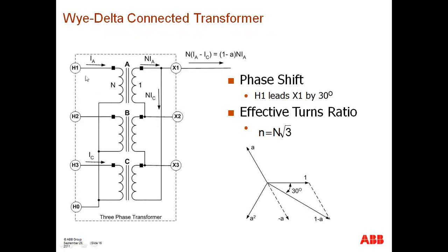the voltage here on this winding connected on Y in relationship to the voltage connected on the secondary winding. Take a look and see that in this particular winding, we have the non-polarity lead of phase A winding connected to the polarity lead of phase B winding. The non-polarity lead of phase B winding is connected to the polarity lead of the phase C winding. And then the non-polarity lead of C winding is connected to the polarity lead of phase A winding.